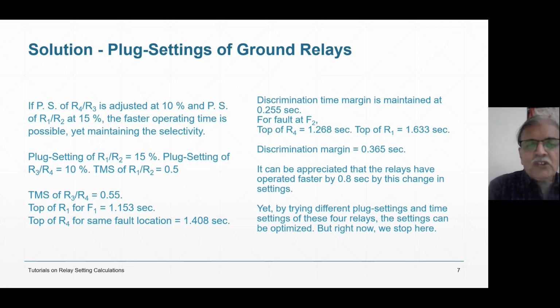And yet relays should operate very fast. Discrimination should be maintained, and the correct operation of relays has to happen. And as I was telling, in a very large interconnected system, for some fault location, maloperations are occurring. Maloperations have not been able to be avoided till date.